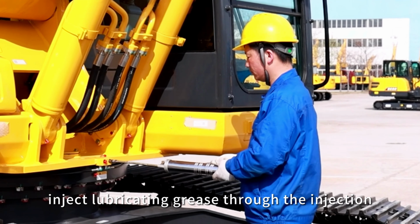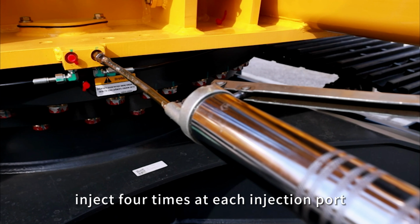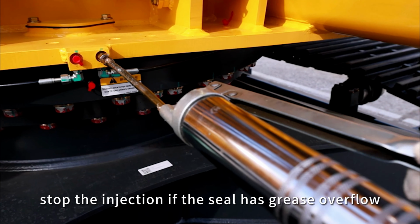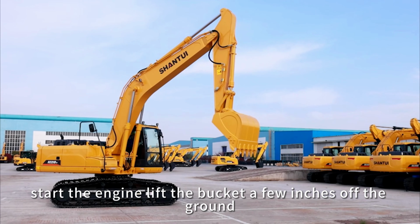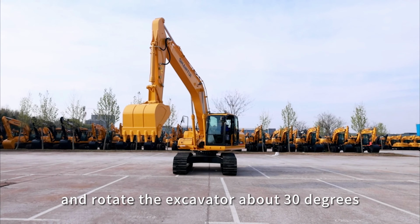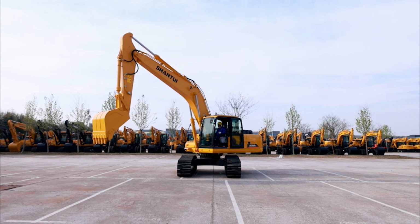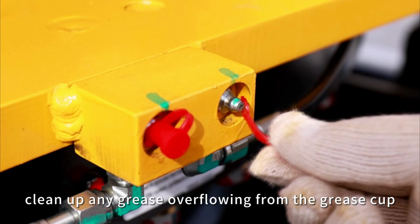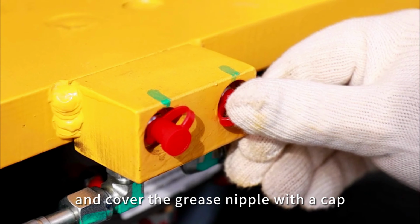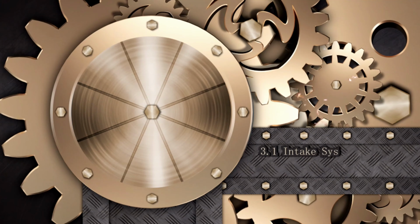Inject lubricating grease through the injection port with a manual grease gun. Inject 4 times at each injection port. Stop the injection if the seal has grease overflow. Start the engine. Lift the bucket a few inches off the ground and rotate the excavator about 30 degrees. Repeat the above steps twice. After the grease has been injected, clean up any grease overflowing from the grease cup and cover the grease nipple with a cap.